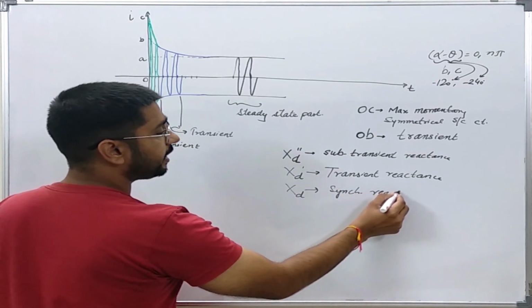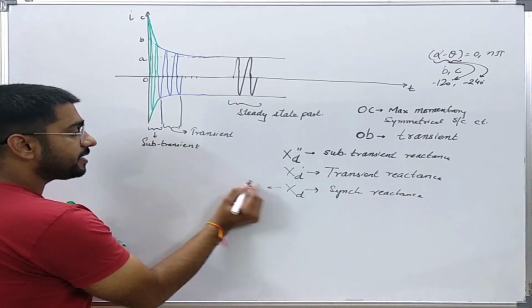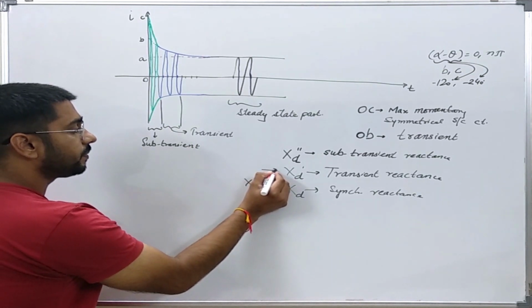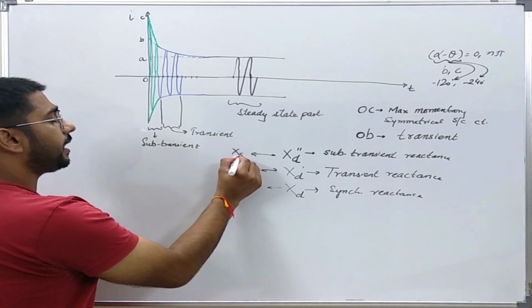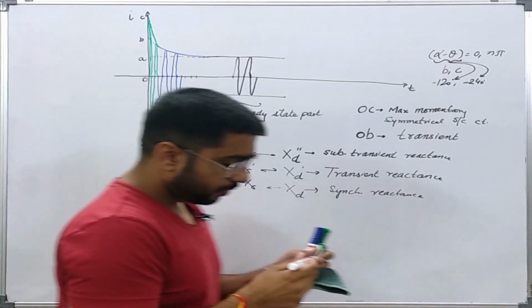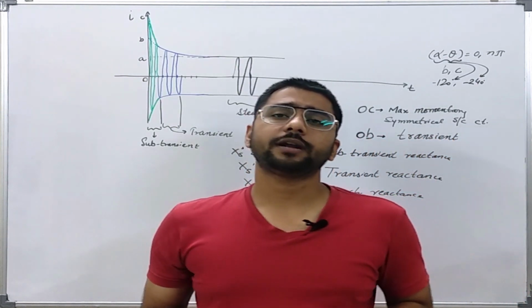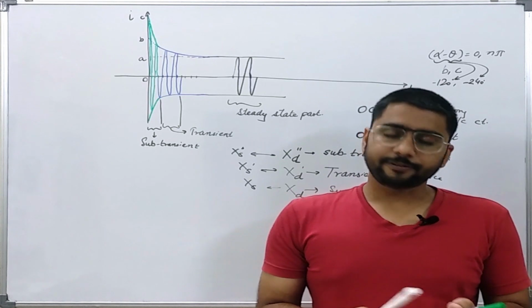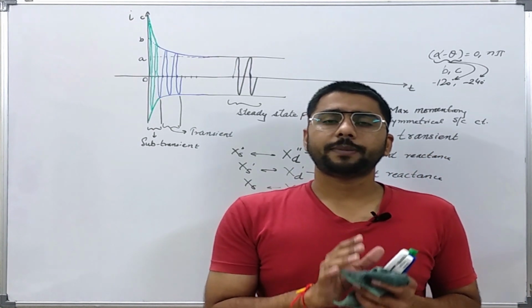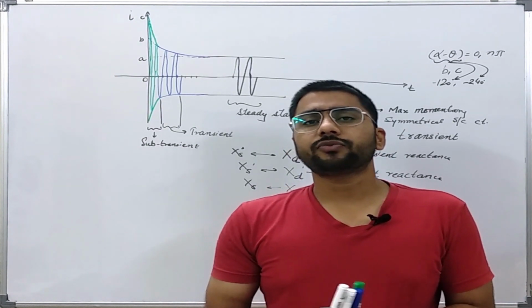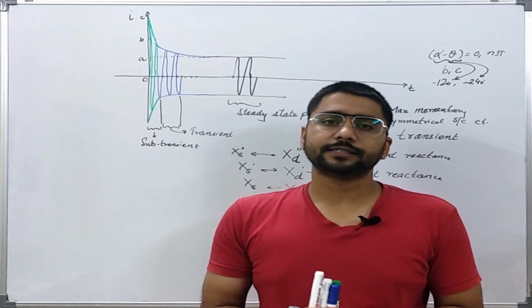the steady state reactance. Now for a round rotor machine, this can be replaced by simply XS, XS prime and XS double prime. Now we will study it in detail when we study the synchronous machine part in our electrical machine course, that whenever we are dealing with that current which is approximately 90 degrees out of phase with the induced voltage, then we take the direct axis reactance.